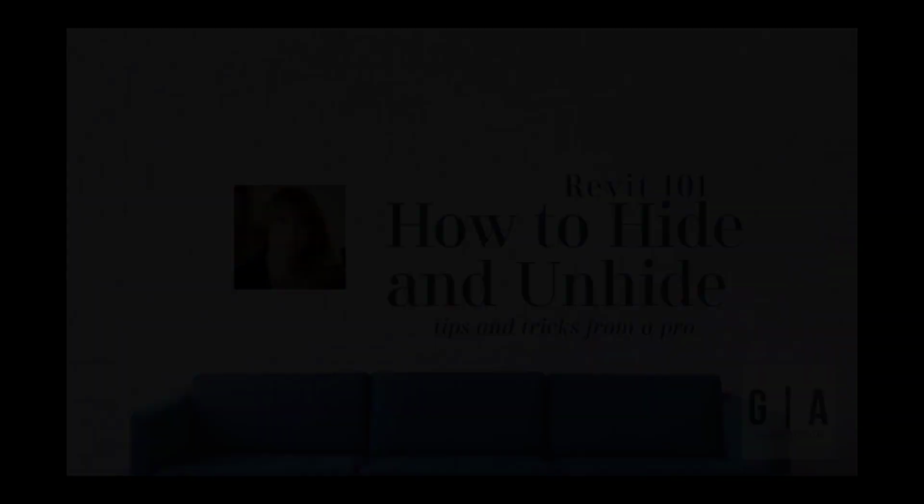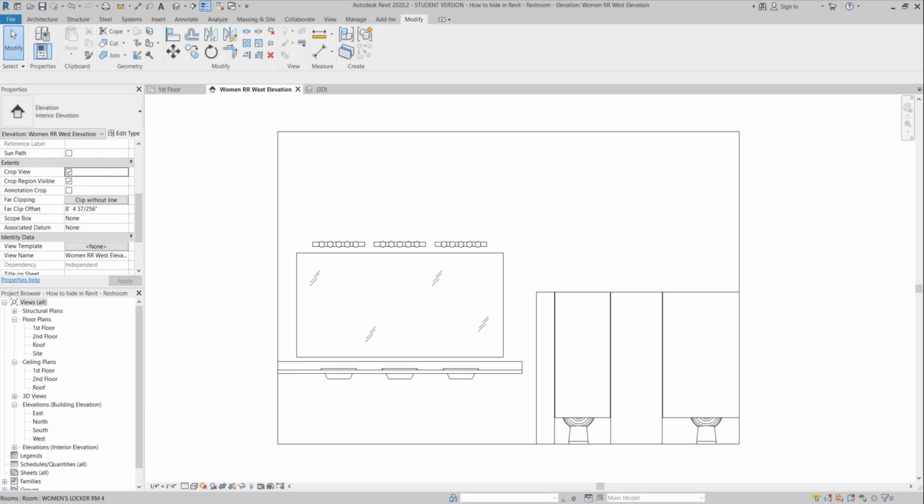Today I have a quick tutorial on how to hide and unhide elements and components in Revit. There are a couple of ways to hide and unhide in Revit. After you watch this video, you will have a good understanding of both methods. In this example, I am working on a restroom elevation. I'm running into a problem with items being in my elevation view. I can either hide items temporarily or on a more permanent basis while I work.